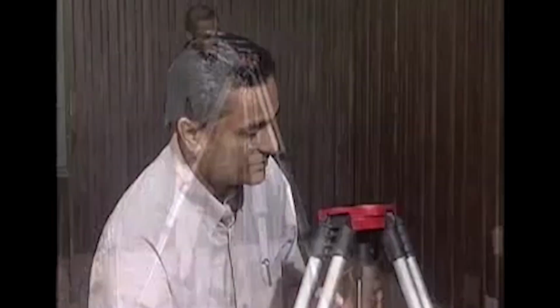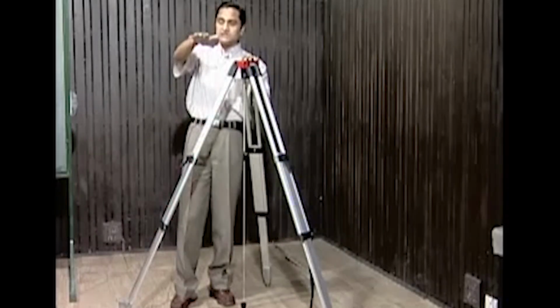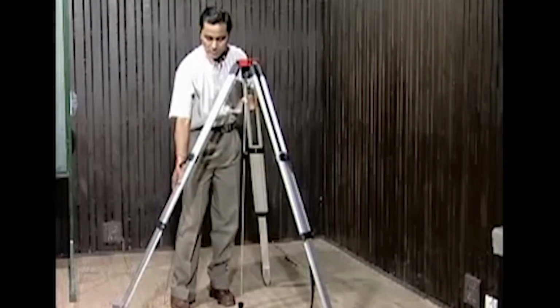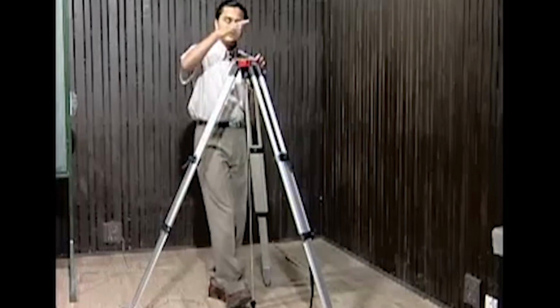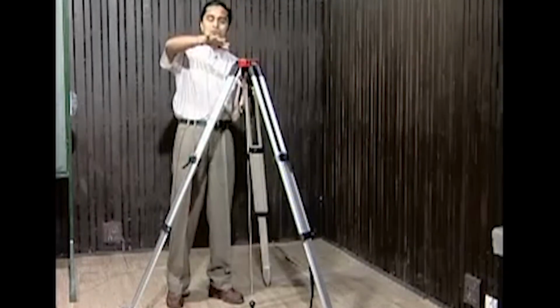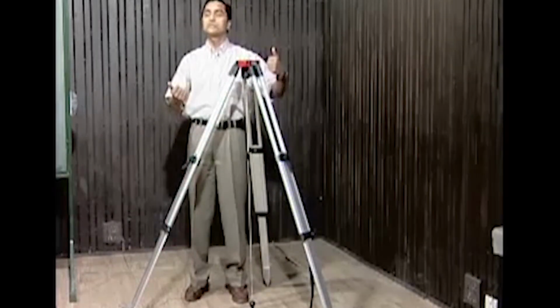It's by visual examination. Now there are two movements of the tripod legs. One, I can move the tripod leg circumferentially. Basically, when I move it circumferentially, what happens? It will change the leveling. It will not change the centering. So if I move it circumferentially like this, generally the centering of the tripod will not change much, while the tripod head will change its leveling. So I can do it for any of the three legs depending on the requirement.